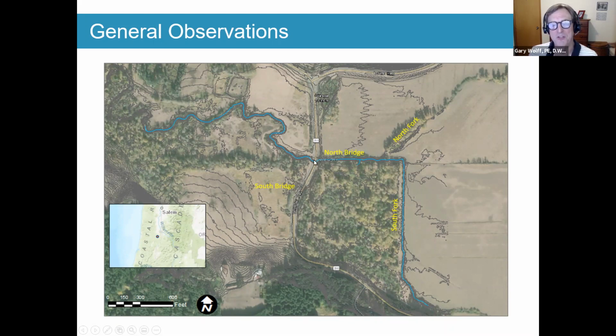They want to raise this road up, and of course in doing so they're increasing this sort of dam you can think of across the floodplain. So we helped the county figure out how to provide enough conveyance through that raised road that we would meet the design objectives.